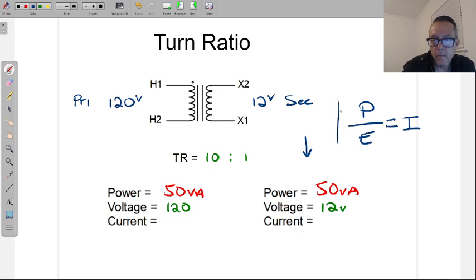That's a very useful Ohm's law because I is always what we're looking for. We're always looking for amperage. If we're going to buy a breaker, we need to know amperage. If we're looking for wires, we need to know amperage. So this is a very useful form. Now, if I calculate that out, it comes out to 4.16 amps.